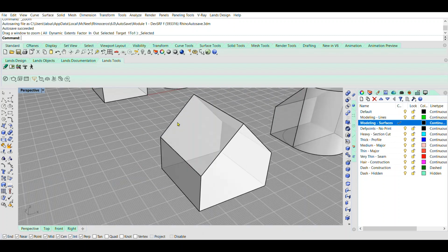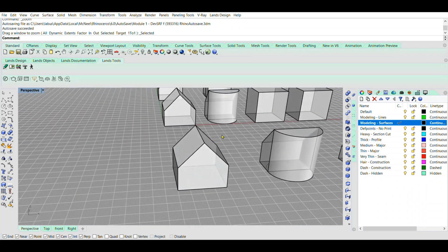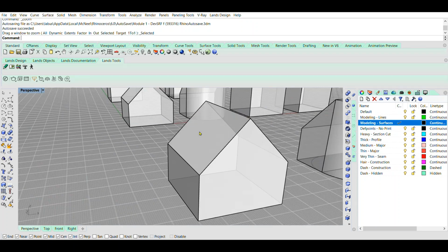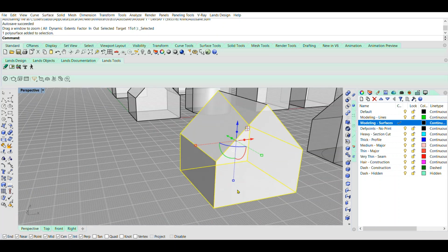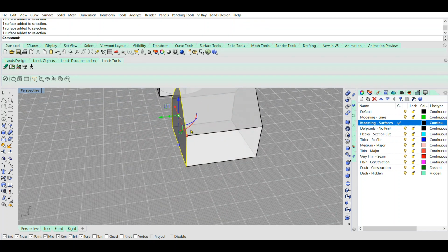So I typed that in on this, and since this one has no curved geometry, I can just use rotate 3D. I'm basically going to take this one apart, rip it apart, but just flatten it out. I'm going to imagine this bottom piece is flat, and then take apart all sides. So first I'm going to type in explode, and then you'll see it's exploded into 5 surfaces. Each surface is now unique to itself.